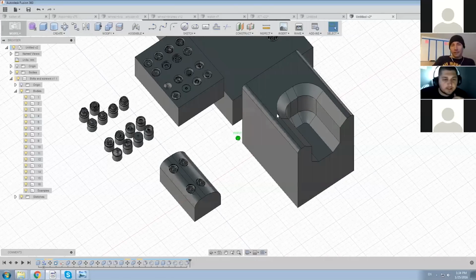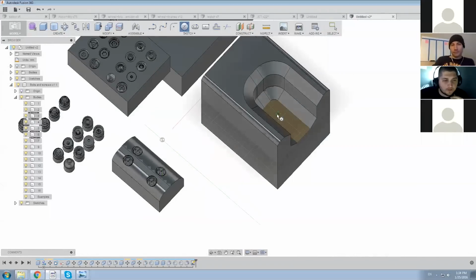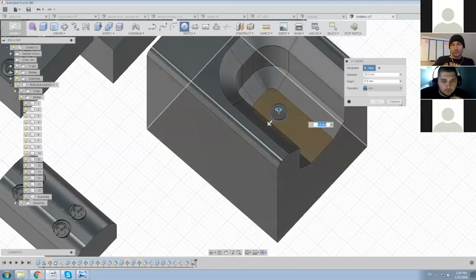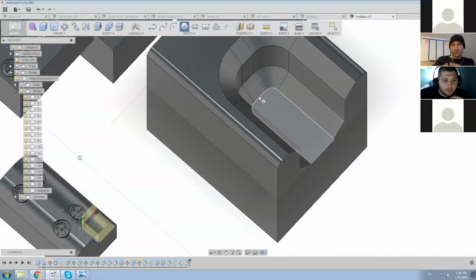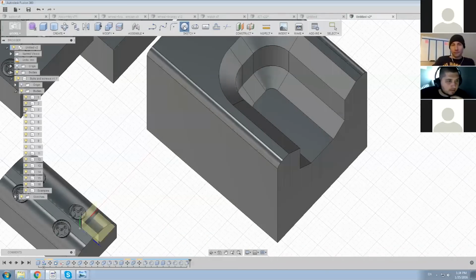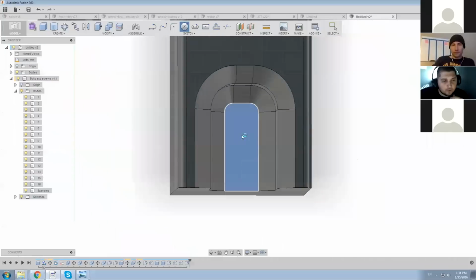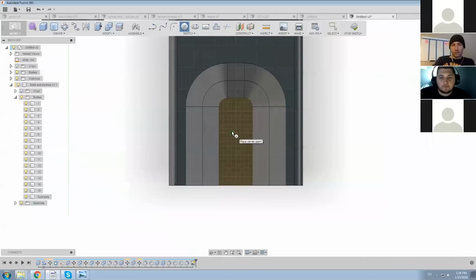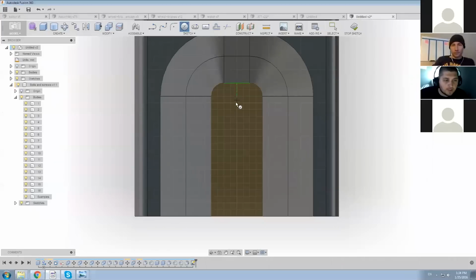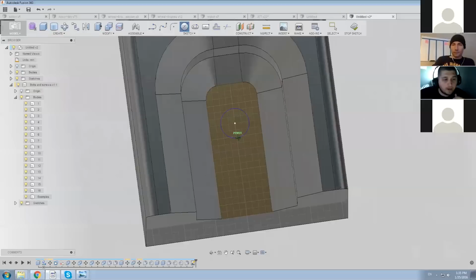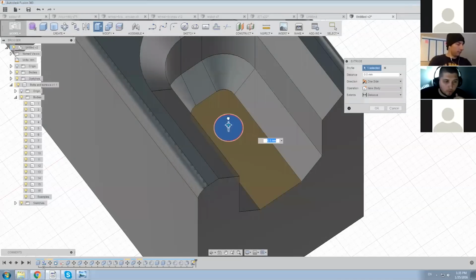Absolutely. Let's say if I wanted to create a bolt inside of this cut, first of all, Fusion will tell me exactly, let's say I want to do it with a sketch. Let me cancel that. When I do it with a sketch, I click on the face. It automatically rotated the face for my convenience, right? No program does that. I haven't seen that. And now it will tell me the center of that shape. It only takes me hovering on top of that edge, and it tells me the center, like where I should place it. It's all parametric, which means that it's all controlled by digits.